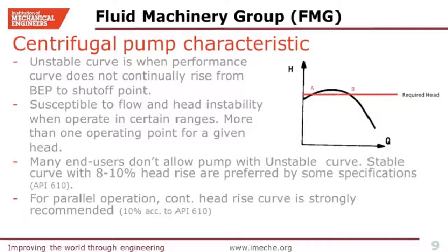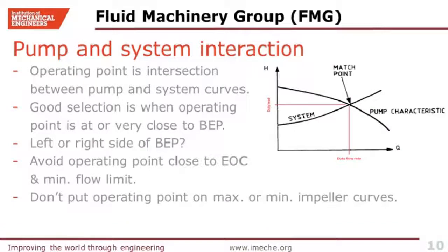I personally have seen several installations with unstable pump curves, which were in service for many years without any problem. This highlights the importance of a system approach when selecting the pump: by carefully tuning pump and system, even pumps with unstable curves can operate without any problem.